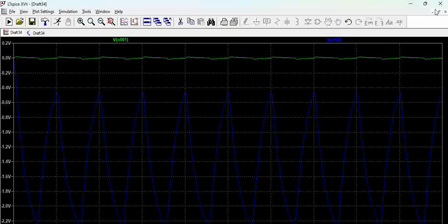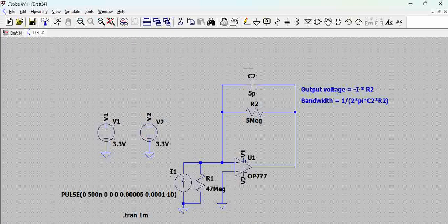So then you can actually play around with the capacitor to see how it is adjusting, and also change the input frequency in accordance with your sensor, and see how the circuit is behaving. And this kind of simulation is very important when you are working on the design, because you don't know what sensor you'll be connecting, so you'll be testing that sensor interfacing with your circuit only when the final circuit is available on the PCB board, right? So before that itself, we can model all the parameters.